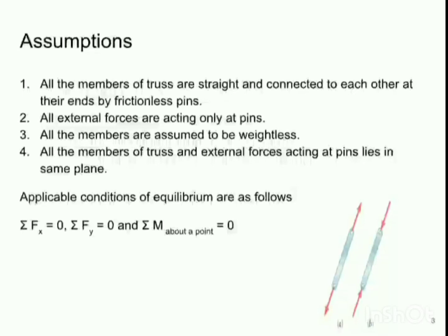Fourth, all the members of the truss and external forces acting at pins lie in the same plane. So this is a very important assumption. So from the second assumption, external forces are acting only on the pins. As we can see in the figure given below, any force which is acting on the truss is applied on the ends, that is at the points where the members are connected, that means at the pins.